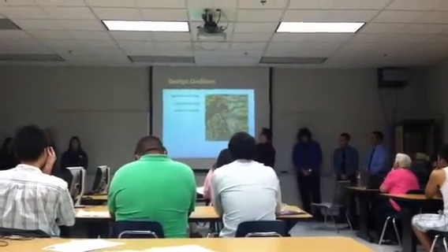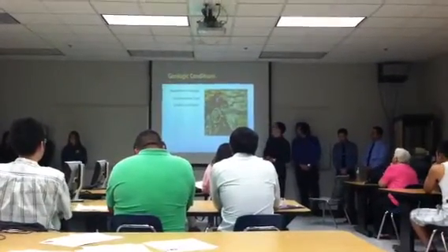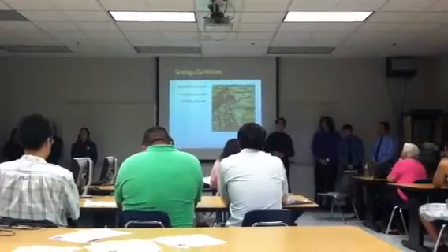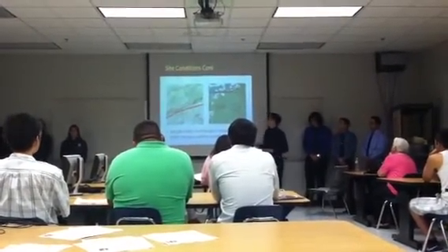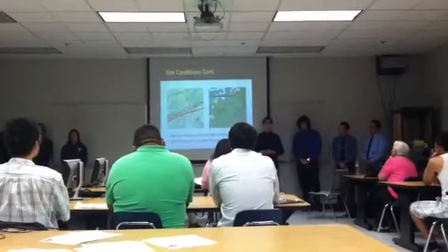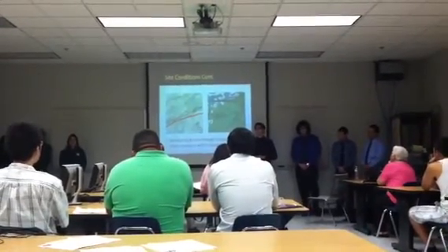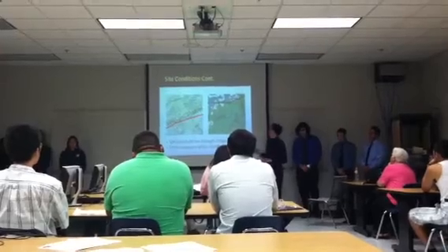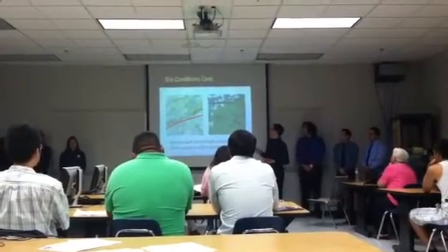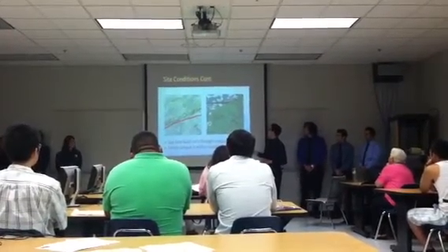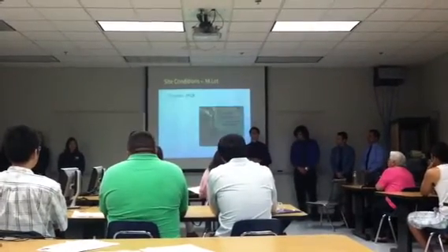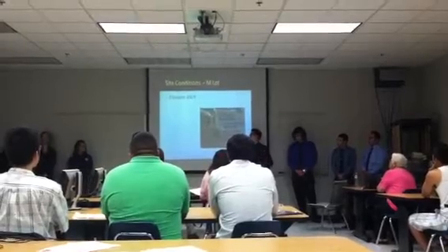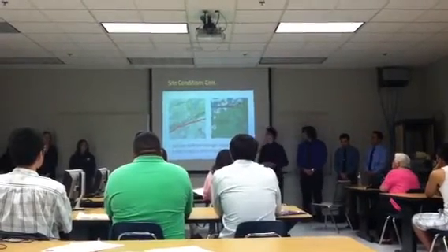This is about historical soils. We have unconsolidated sands and alluvial deposits. Also, with respect to faults and earthquakes, we have one major fault that goes to the campus, and that's the San Jose Fault. And this is a liquefaction map. We can see here that our entire campus is within the liquefaction zone. We also know that our water table levels range from 2 feet to 20 feet.